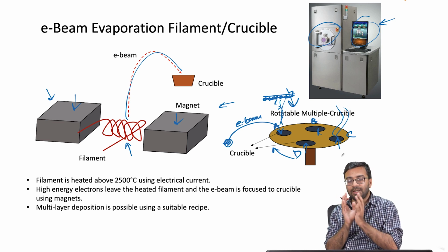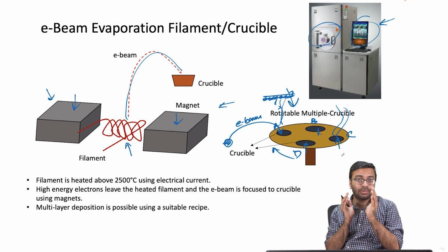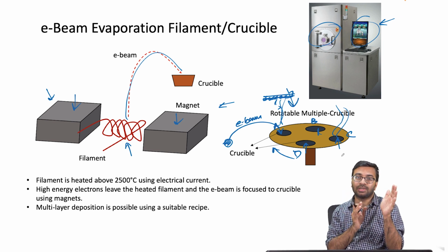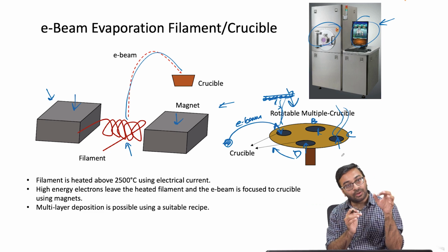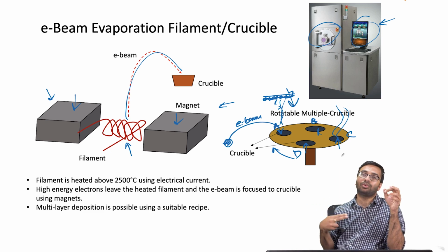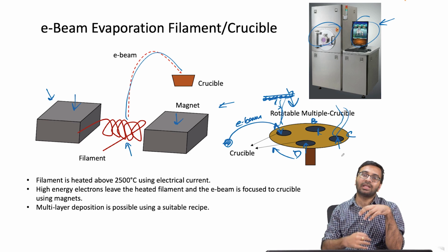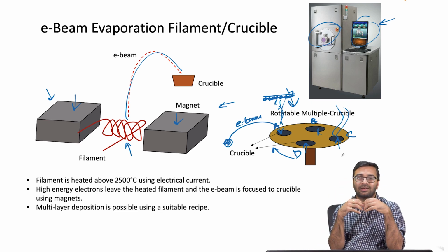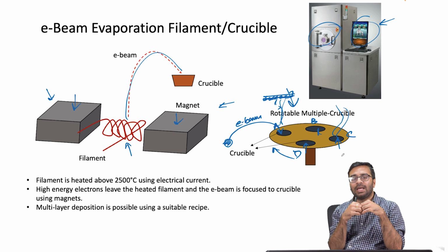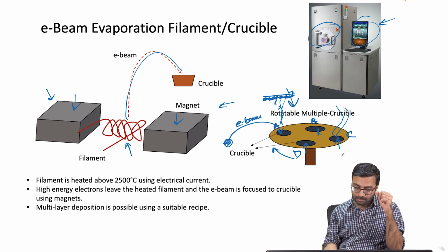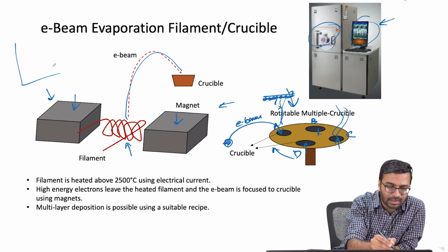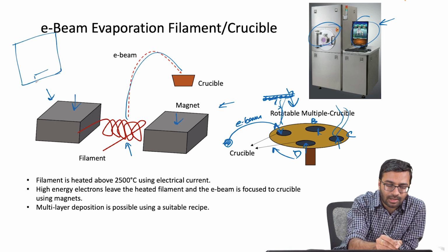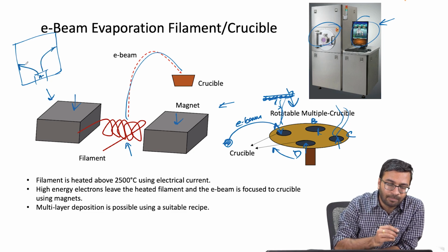So it's very important that if you want a sequential deposition in a thermal evaporation system, you vent or break the vacuum, take the source material out, put a new source material, again do the vacuum, again start deposition. So it's a lengthy, time consuming process, and one of the major problems is, for example, when you start a deposition, say if this is the vacuum chamber, and once you start deposition, material A also will get deposited on the walls, right.